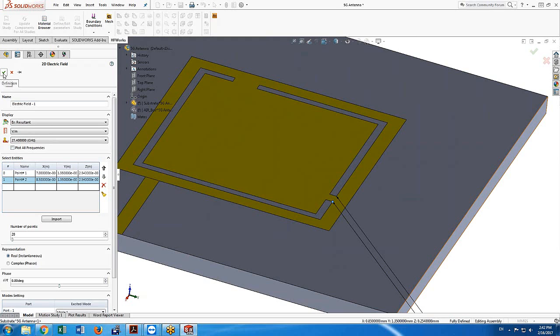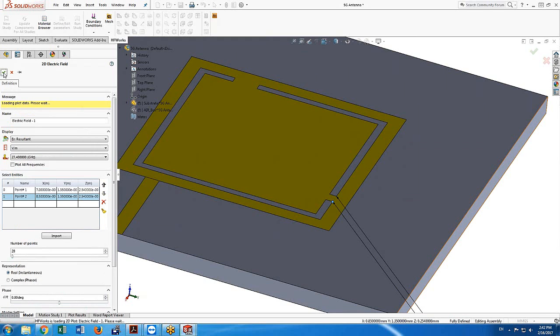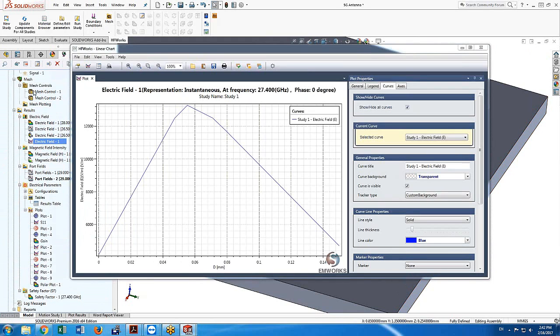It's just these 2 points, I can select more, and then I can plot the electric field or all the near field data, as a matter of fact, in any segment. So I know at least in the middle of that gap, the electric field is maximum. Not only do I know it's maximum, I know its value, because the color plot is nice.